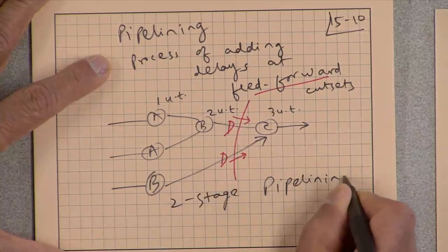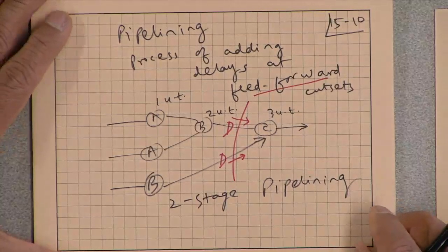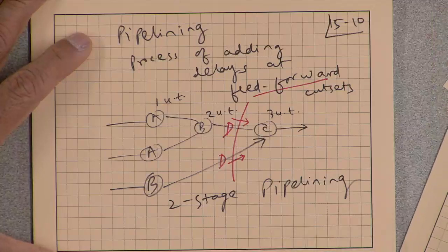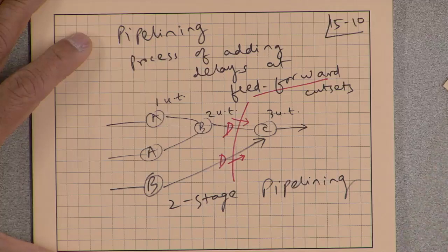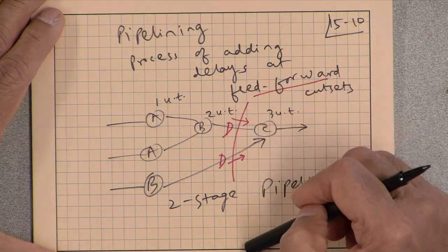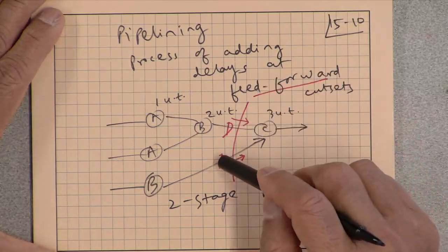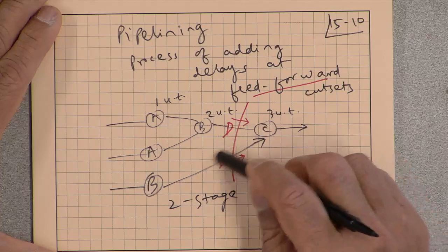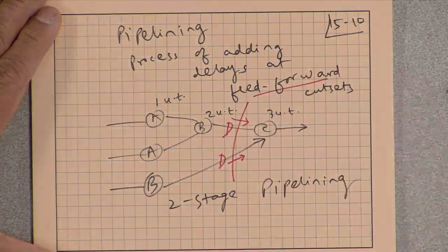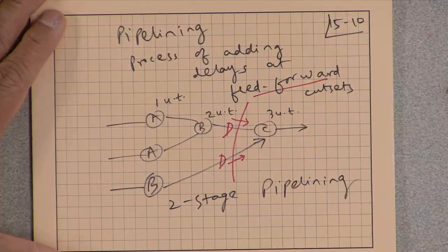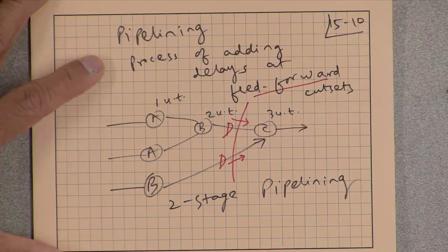In your homework this week, you are taking the fast parallel structures where there was a multiplication by x squared in the time domain, and that was not implementable, so we need to make it causal by creating a delay element there. The way to create a delay element is to find a feed-forward cut set and place that delay, and the delay along with multiplication by x squared, or x cubed in 3-parallel, becomes a switch, and all other delays stay as they should. So that's a brief intro to pipelining. We'll talk more about this next class.